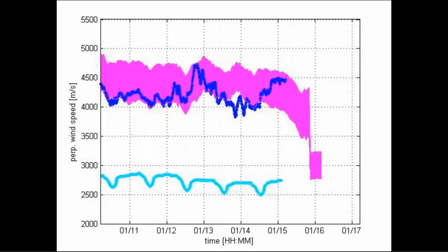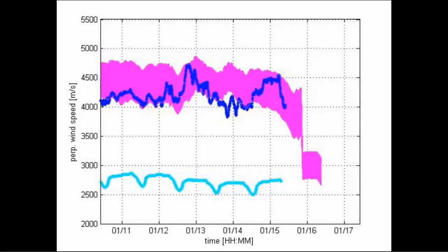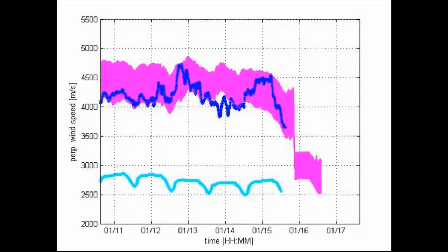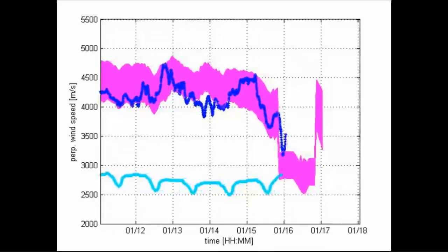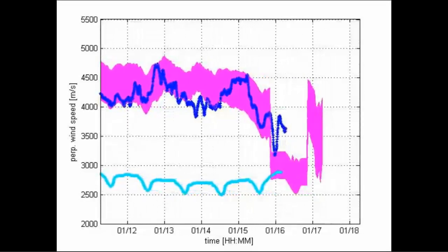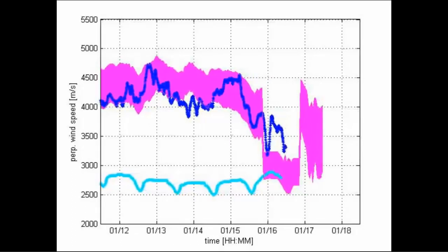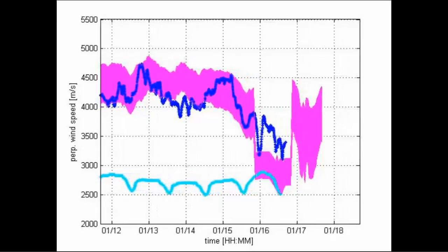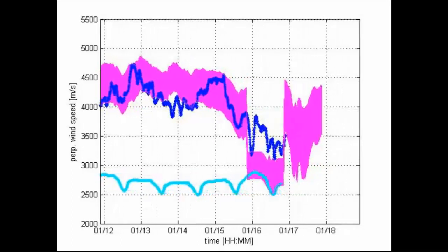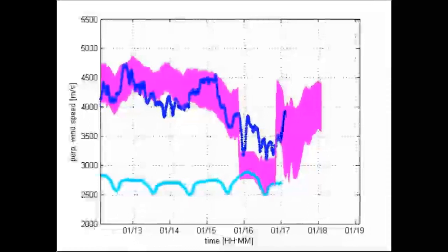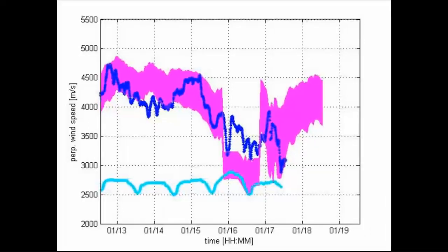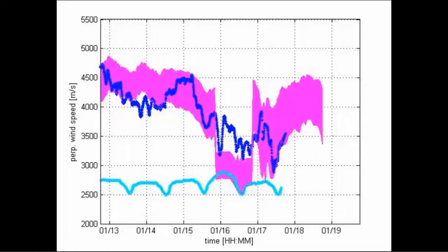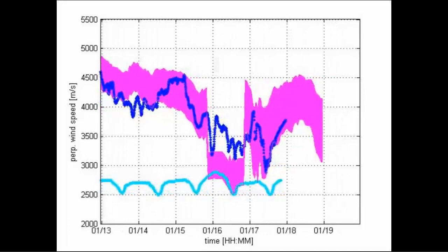So at the bottom, the light blue curve is what we call the ambient adjusted rating. You can clearly see it's based on temperature, basically. You can clearly see the 12 noon peaks, when the temperature is maximum and the sky may be blue with maximum solar radiation.